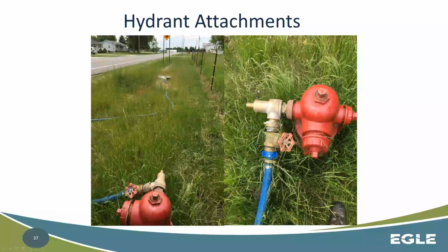So this is a fairly interesting setup. I'll just tell you that while I can see what they're trying to do is kind of control the flow of the water into a path they want, as you can see, we're getting standing water conditions down here. So this actually could become a cross connection because this is not an ASSE certified backflow preventer. This is a blow-off valve, right? We have direct connection and can actually get submergence of the end of this outlet. So this is not an ideal setup for a blow-off valve in a distribution system.